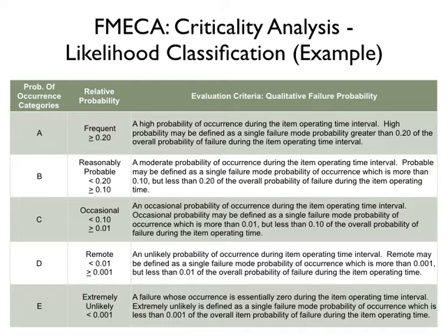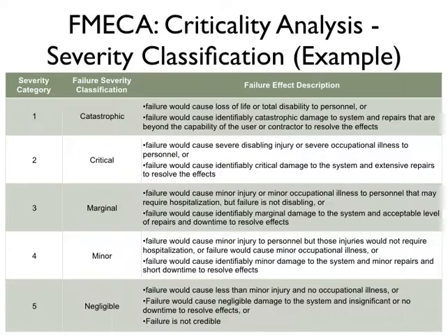Right? And so again, for each failure mode, and this is in lieu of doing the FMEA style, because if you're doing a FMEA, you're only going to quantify the risk using RPN values. If you're doing a FMECA, for each failure mode you're going to be choosing one of these categories. So that's the first step for the criticality analysis.